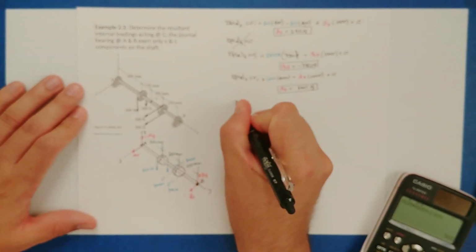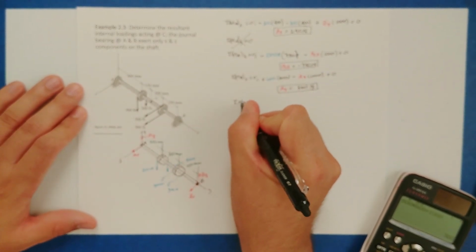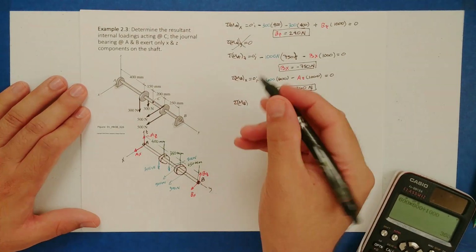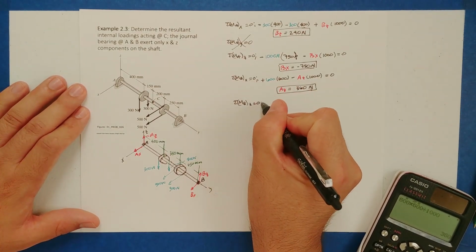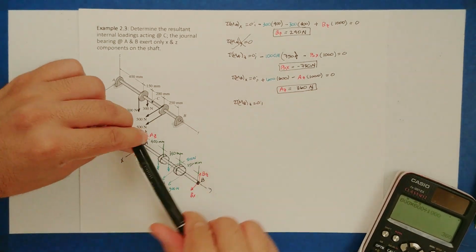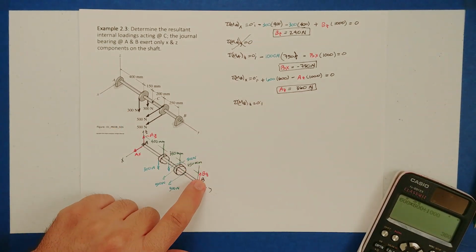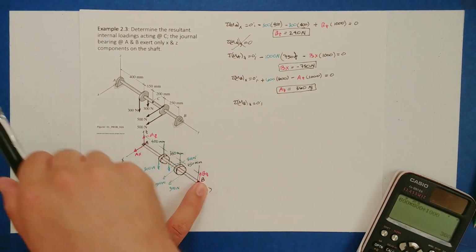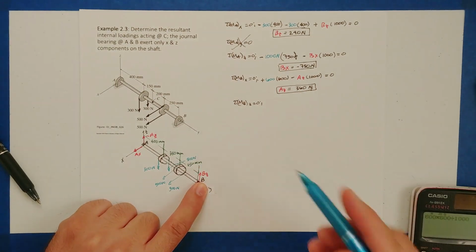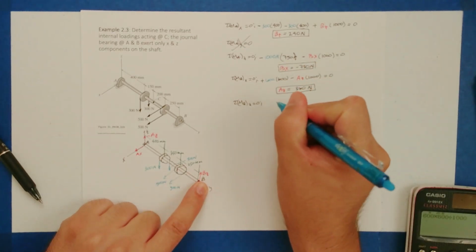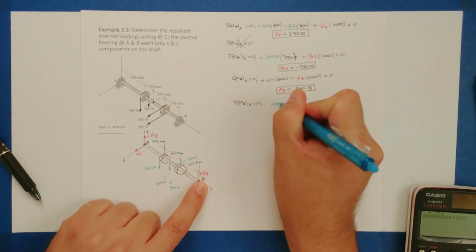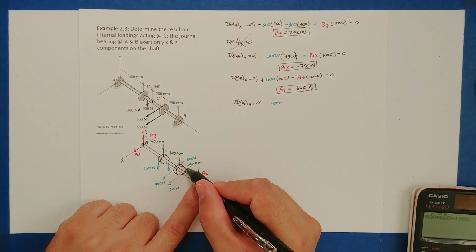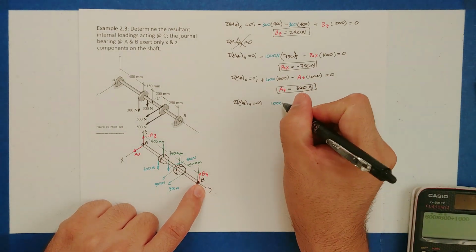Now let's go ahead and sum moments at point B. We already know that about the y-axis doesn't do us any good, so let's do now about the z-axis and make it equal to 0. Now we're looking for these types of rotations at point B. So what do we have sweeping away? We have 500 and 500, or we can take the resultant of those two, principle of moments, 1,000 times the distance to point B. From here to point B is 250.